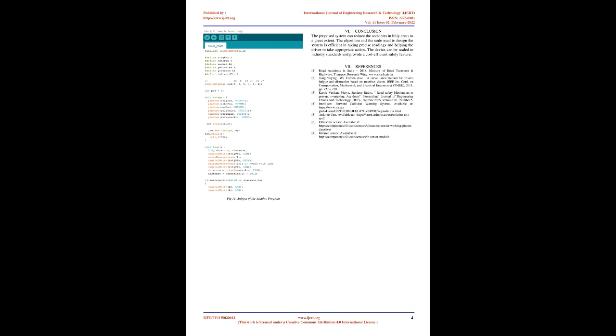When light strikes a photodiode, it conducts and functions as an IR receiver. As a voltage comparator, the IR sensor uses an LM358 operational amplifier, op-amp. The comparator compares the photodiode's series resistor voltage, pin 3, with the preset threshold voltage, pin 2. The variable resistor is used to tune the distance detection range for the object. The VCC pin receives a 5V DC supply, and the negative supply is linked to the module's GND terminal. When an item is detected within the IR sensor's range, the output LED illuminates and remains off otherwise.